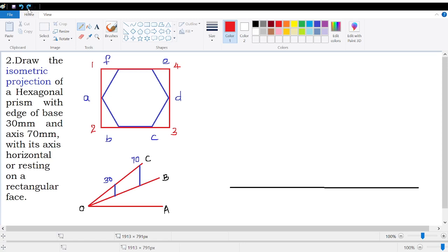First I am drawing the baseline. Then I will pivot this at point 3. You should imagine that this lamina is vertical. Vertical in the sense 2, 3 and 1, 4 will be horizontal, so they have to be drawn as 30 degree inclined lines, whereas 2, 1 and 3, 4 will be vertical themselves. So I am first pivoting at the point 3 since it is at the leftmost end.